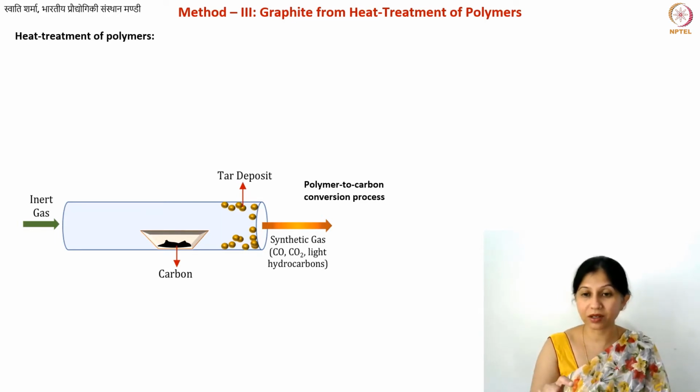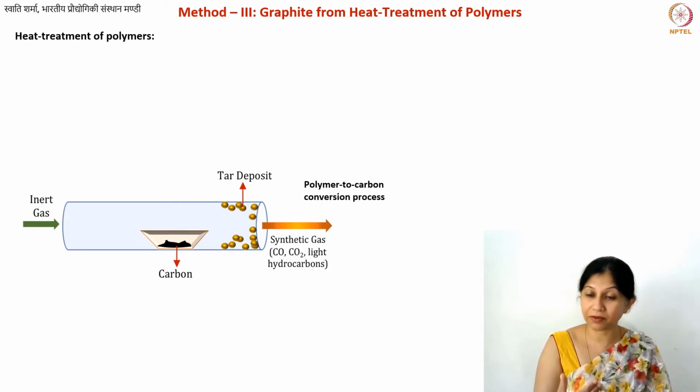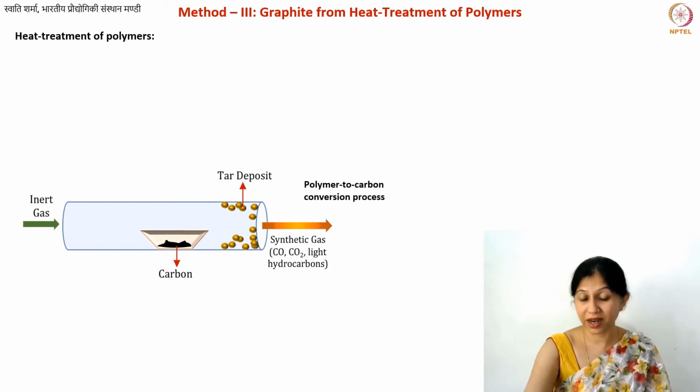Quartz will typically not survive above 1200 degrees. Even depending upon the quality and the defects, it might melt slightly earlier than that, but up to 1200 typically it survives. But if you want to use a very high temperature furnace, for example, up to 1600 degrees, or in the case of graphitization, typically 3000 degrees, then you will use ceramics. Initially up to 1600, up to 2000 degrees, typically alumina, and above that you might also consider silicon carbide. In extreme cases, you might even use a tube made of a certain type of carbon material. Then it can really withstand very high temperatures.